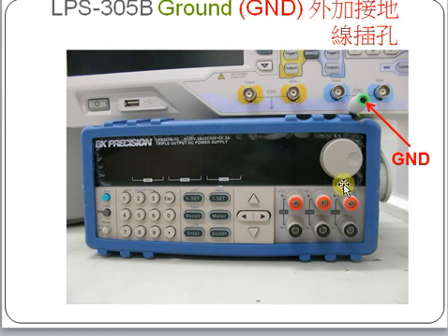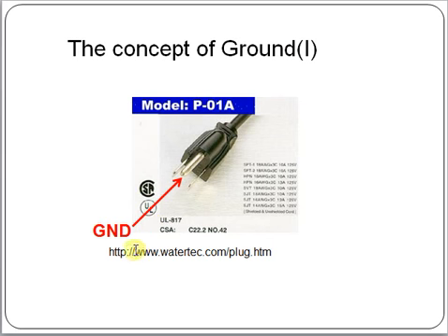So we will use a wire to connect the ground from outside. Connect it to the oscilloscope ground. This is connected to the endpoint of this plug. Every electric device in the building will have the same ground because they're all connected together.